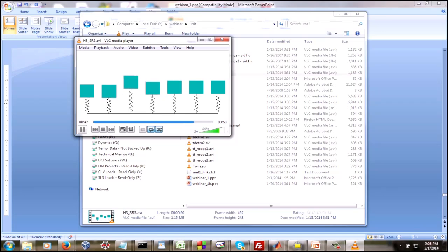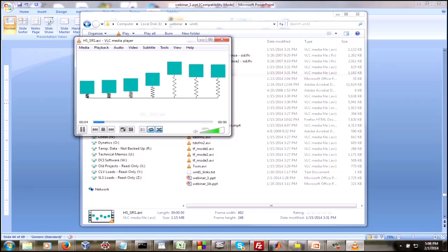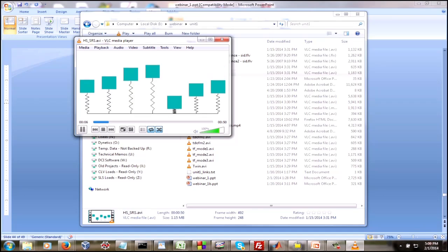In many cases, inertial navigation systems already have internal isolators for their sensor heads. So if we isolated the outer portion of the box, we'd effectively be making a two-stage isolator, which may or may not cause some problems with the control algorithm and its accuracy. So check it over with the vendor if there's any doubt.